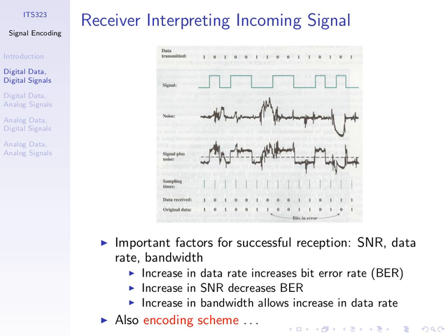If the noise increases, there's more chance of errors. If our data rate increases, there's more chance of errors. Consider in this case, the 2 errors occurred because of these large pulses of noise. This large part of noise meant the bit 0 changed to bit 1. That was a bit error. And this large piece of noise caused a bit error.